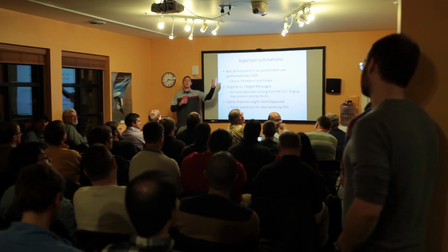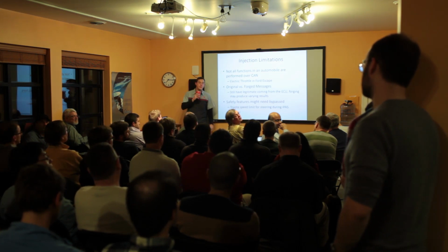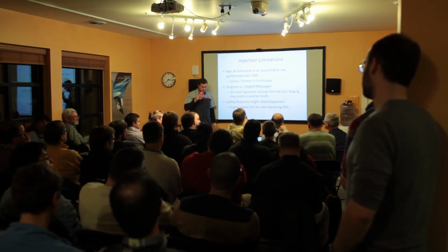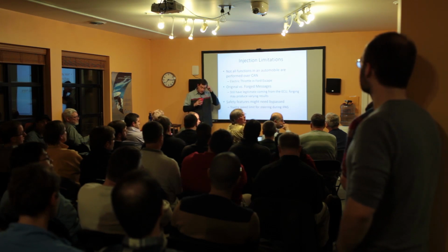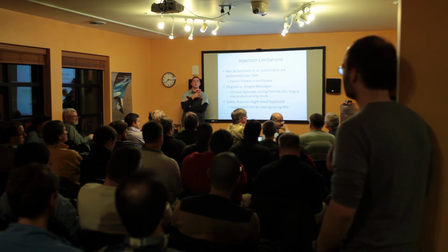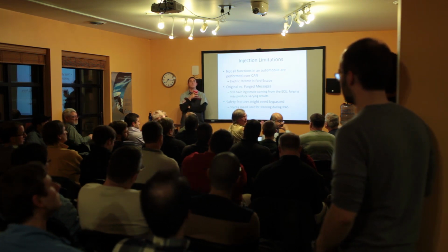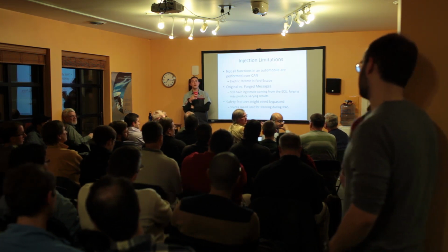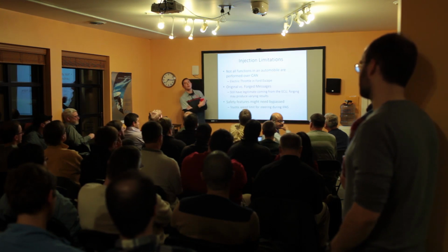Yeah, but the higher priority ones are going to be different than the originals, right? What happens, for example, is the steering angle signal is tied to the ID, the address. So you can't use a higher priority one because it's using that exact address for that value. Yeah, like the steering ID in the Prius is 25.